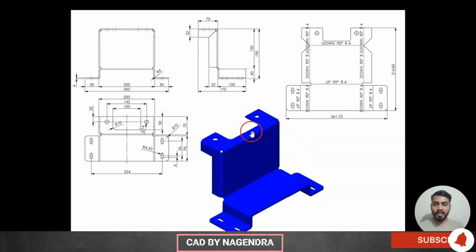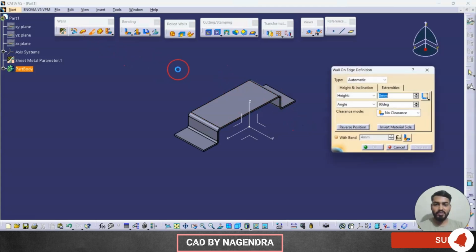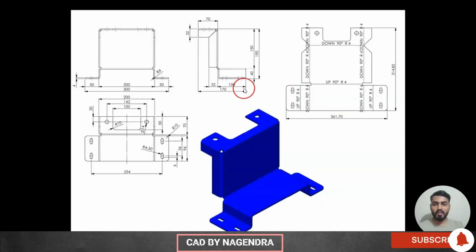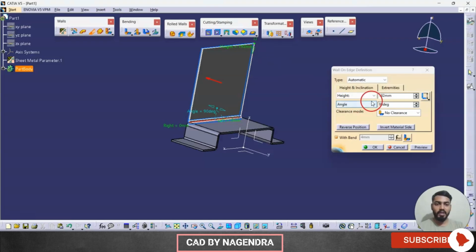After creating the base, as you can see on this left side view, we have exactly a 90 degree edge flange from this end. So I'll go here with the edge flange from here towards the upward direction. This height we want to mention here. You can see from here to here the height is 150. Let me give this height of 150.